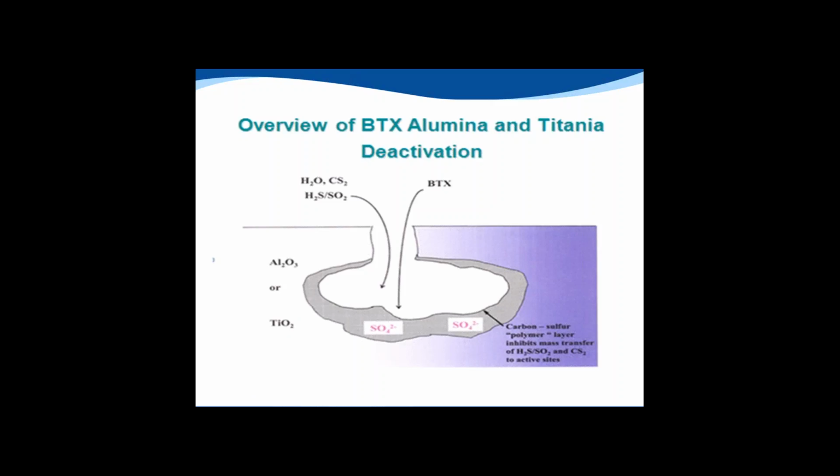There is a rejuvenation procedure, and if anyone has any questions on this, we do have a paper. A rejuvenation procedure would, instead of running a 2-to-1 H2S to SO2 ratio in our SRU, increase that ratio to, say, maybe 8-to-1. So we would have much more H2S in our process gas streams compared to SO2. The purpose is that this enhanced level of H2S would react with the free oxygen that's present in our bed.